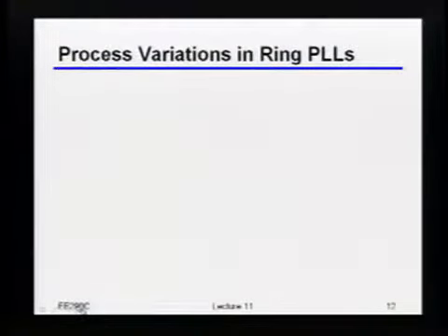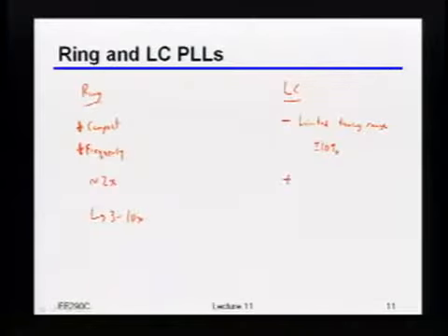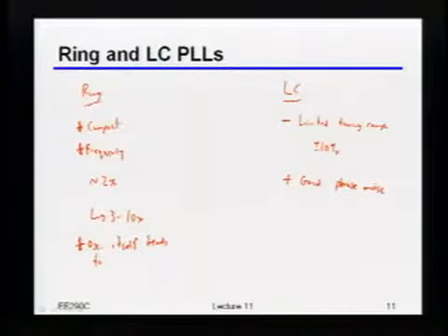Okay? So let's think about that a little bit more carefully. If I take that ring oscillator, and I should have put a 1 plus here, which is, of course, good phase noise. That's obviously kind of important. Well, the ring oscillator itself tends to be dirty, and the reason is that, since everything and its brother can move it around, it will.